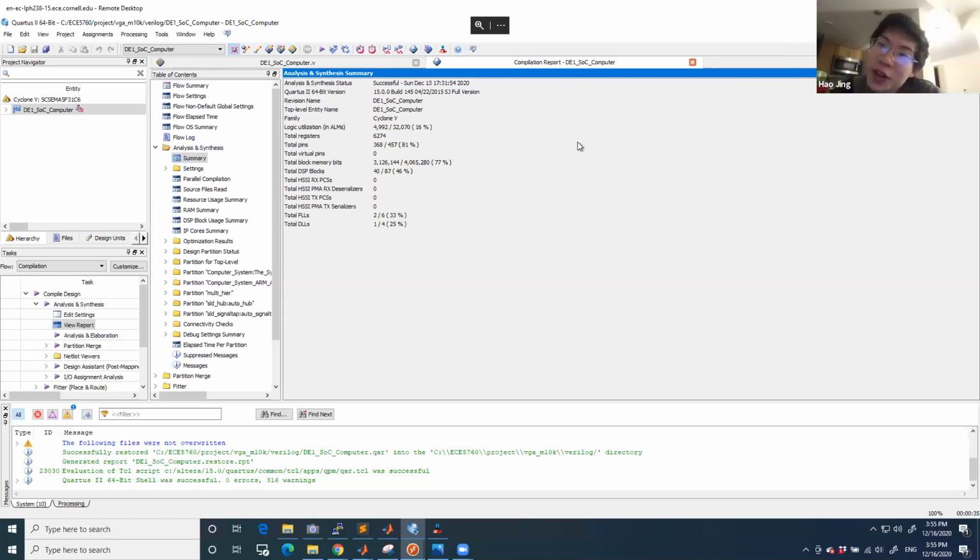Our final point is that if there were something like ModelSim on the chip, it would help our debugging, because the SignalTap sometimes really didn't help. Yeah, because you have memory limitations. You cannot run too many samples, and you cannot see too many different lines.